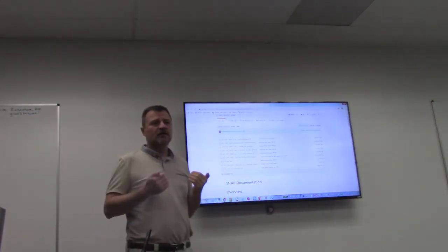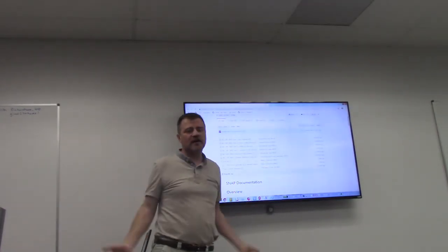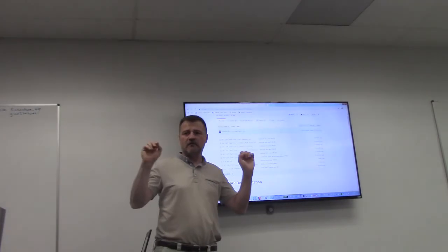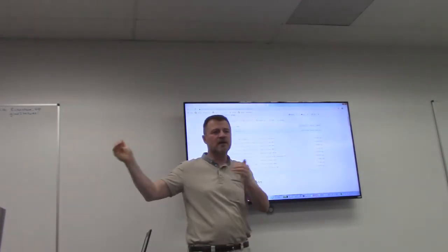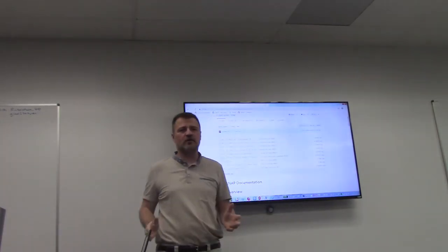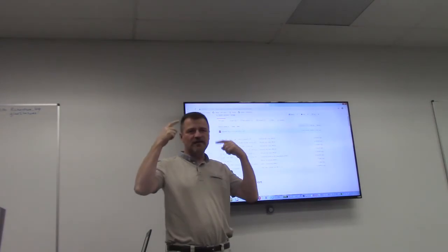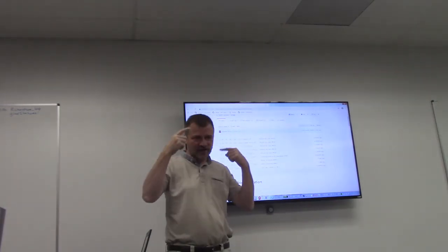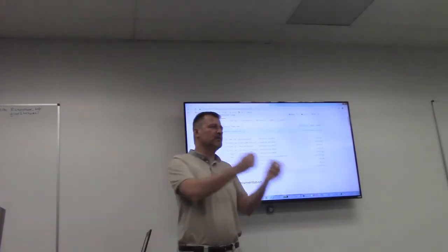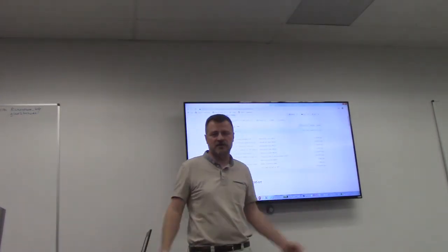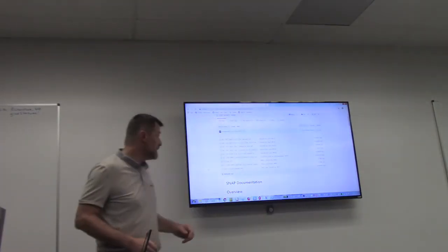That's for HLS, to ease the transformation process, because not everything can be converted. For example, a very small detail: if you have a clock access to the host memory, the FPGA doesn't know the clock of the host system. So anything that is clock related needs to be reworked, rethought. We cannot take a clock dependent action and put that in an FPGA. The FPGA doesn't have the time of the system. Or you need to write a routine for that.